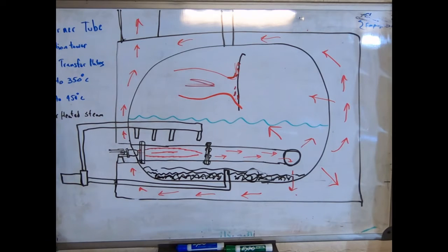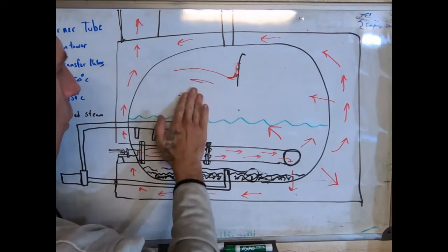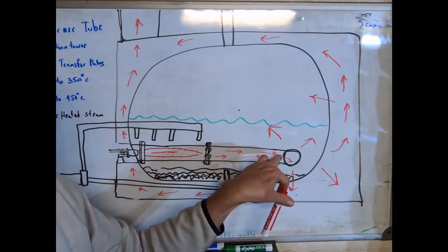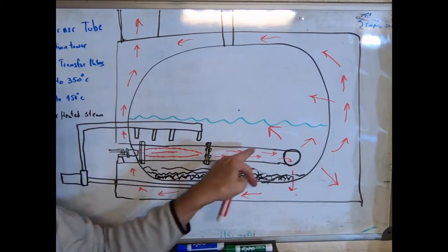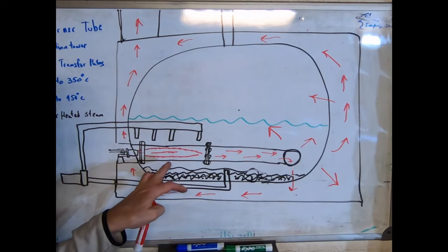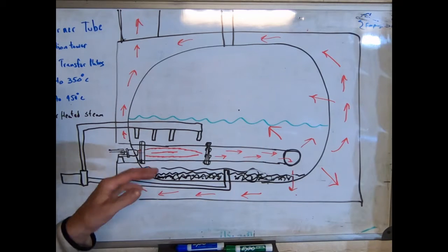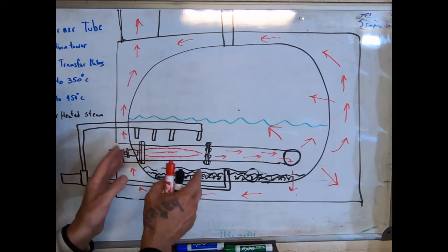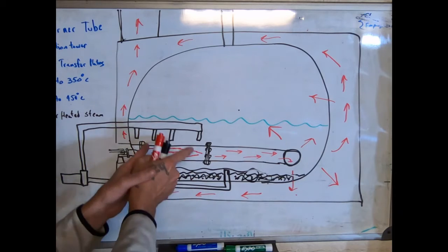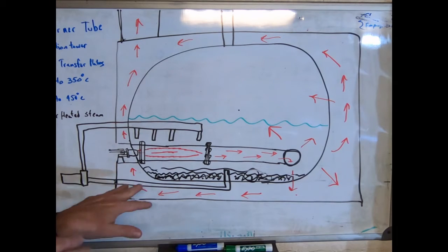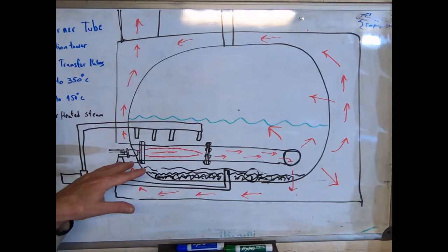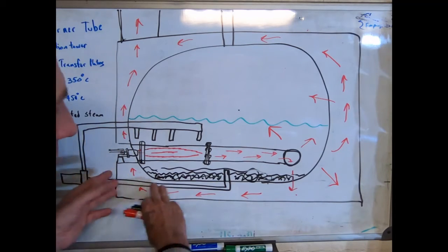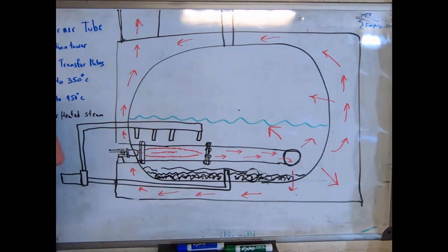So that's an issue. So one way we have to mitigate that is we have a flame tube going through the boiler. This is a very common process. A flame tube is a very known industrial piece of equipment, and it usually has an extractable section that can be removed from the system before it becomes completely destroyed and replaced during an outage or any other cleaning that needs to be done on the bottom of this tank.